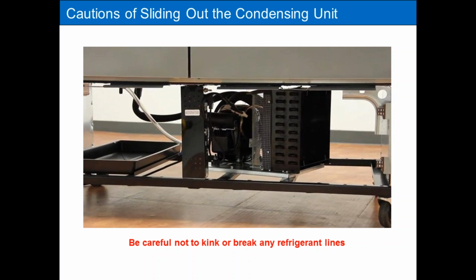Recently, I was working on a cooler, a beer cooler, where the same scenario happened to me, but I didn't realize the problem until actually 2 days after the fact. I had pulled out a condensing unit for a beer cooler just to change the condenser fan motor. So it was a simple fix. Pulled out the unit, changed the condenser fan motor, pushed it back in. It was in a bar, pretty loud, pretty crowded. I didn't hear the magic hiss, but apparently when I pushed the unit back into the beer cooler, the suction line gave free, and all the refrigerant dumped out. I didn't realize it at the time. I pushed it back in, took off.